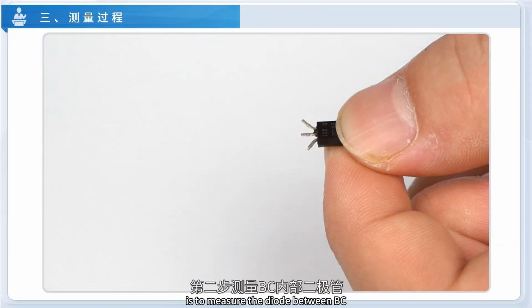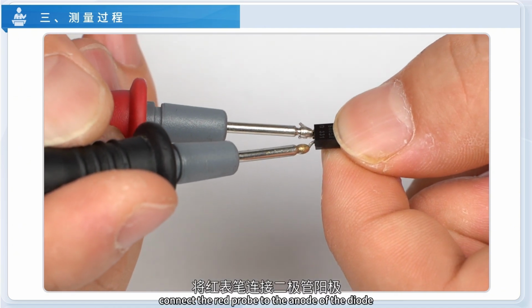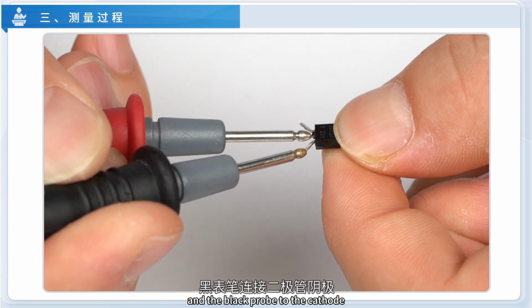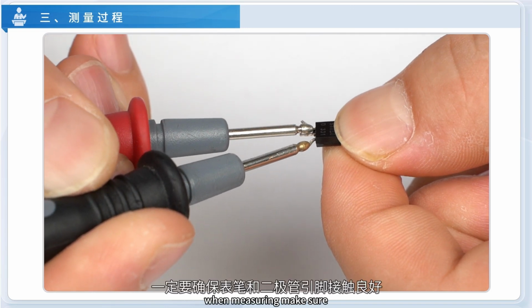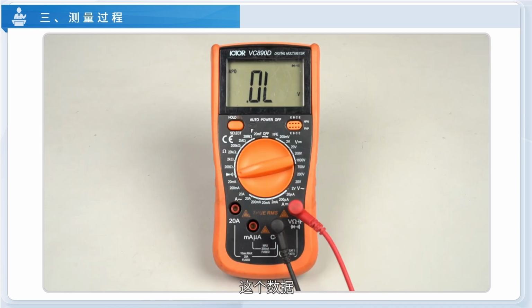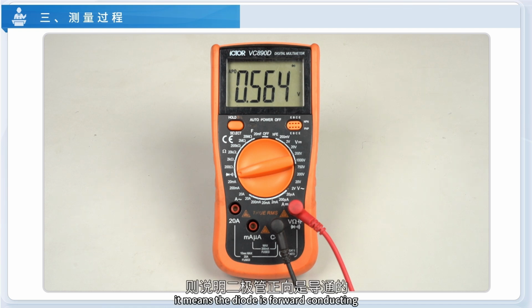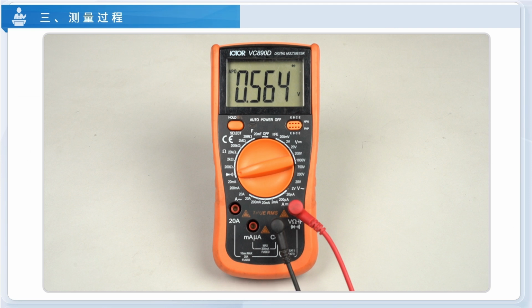The second step is to measure the diode between B and C. Connect the red probe to the anode of the diode, and the black probe to the cathode. When measuring, make sure the probes and diode pins are in good contact. After connecting, check the multimeter display reading. This data is the forward conduction voltage drop of the diode. If the displayed value is between 0.1 and 0.9, it means the diode is forward conducting. The value is 0.564. It means the diode is normal in the forward direction.